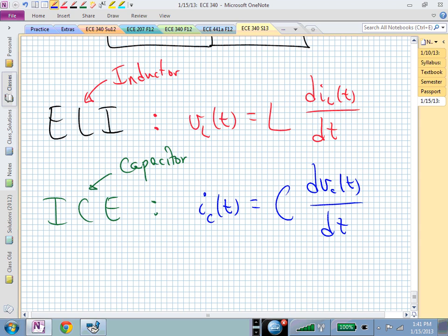I want to concentrate on these variables that have this first derivative piece. Meaning, if somebody says, what are your key variables in this circuit? Then you would go, ELI the ICE man. Voltage across the capacitor and inductor current. So if I can write my equations in terms of inductor currents and capacitor voltages, that'll probably make for a cleaner set of equations. And these we will call state variables in chapter 10.